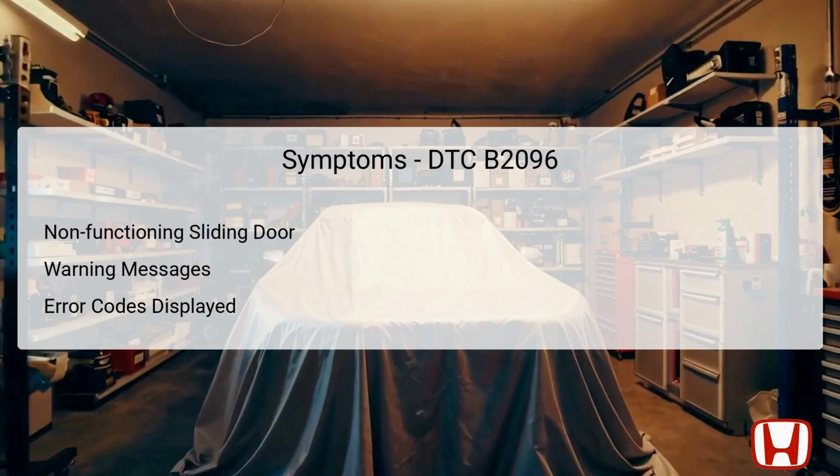Furthermore, the presence of error codes, specifically DTC B2096, will be indicated during a scan with the Honda Diagnostics System, HDS, confirming the malfunction. These symptoms can lead to frustration for both the driver and passengers and necessitate prompt attention to restore the door's operation. Observing these issues should trigger a thorough diagnostic procedure to address the root cause.